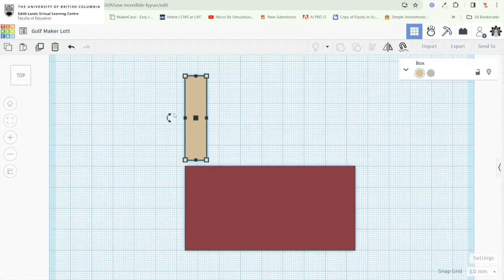So once I've got my top view and my orthographic view, I'm going to take my nice board that I've built here, and I'm going to duplicate it. So this is a new skill. Click on it, and then next to the trash can, up in the left corner, you'll notice there is a piece of paper with multiple pieces of paper behind it. You'll also notice there is a shortcut called Control D. Make sure you click on your 1x4. Let's call this a 1x4. Let's click it, and nothing happens. And you're like, well, that was pretty useless. But check it out. You can pull out your second piece from it.